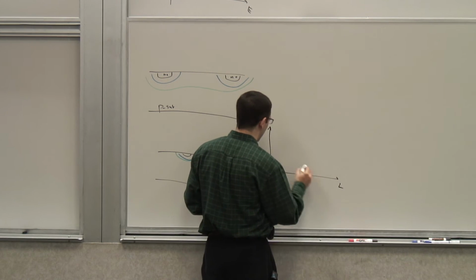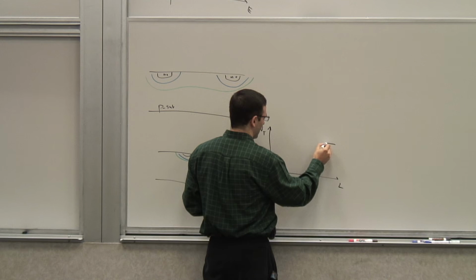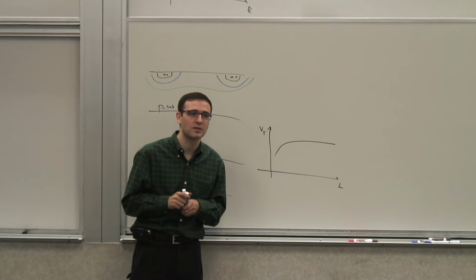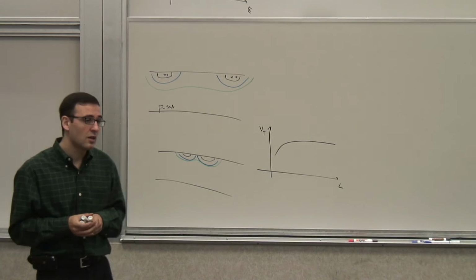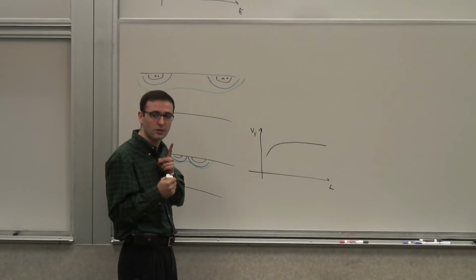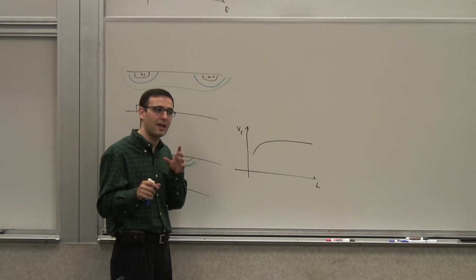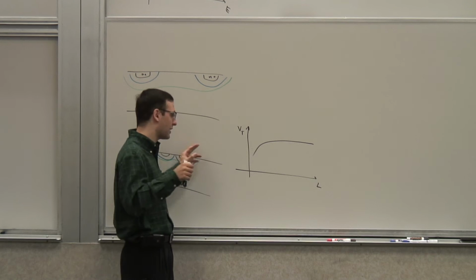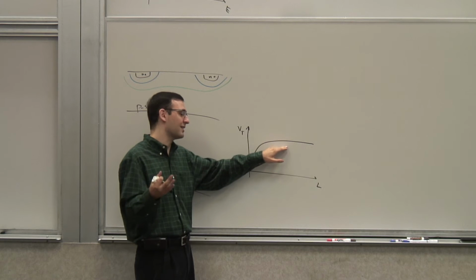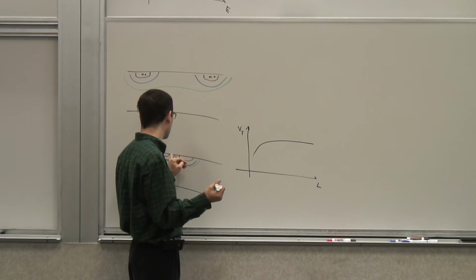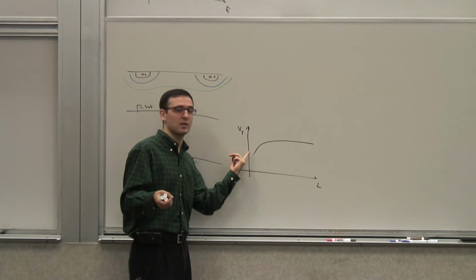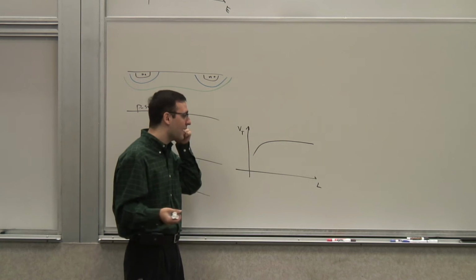So what happens is that if you look at L and the VT, at low channel lengths, VT drops. So how do you deal with that? Well, it depends on what you want your VT to be, because we have this one parameter we control, QI, the implanted charge. At the end of the day, you could implant a certain amount of charge to make sure that you get the right VT. So if you wanted to keep the VT constant, it's not necessarily the case, but if you wanted to, you had to implant more charge. If you didn't want to keep it constant, you just lived with it. But it is an effect that happens.